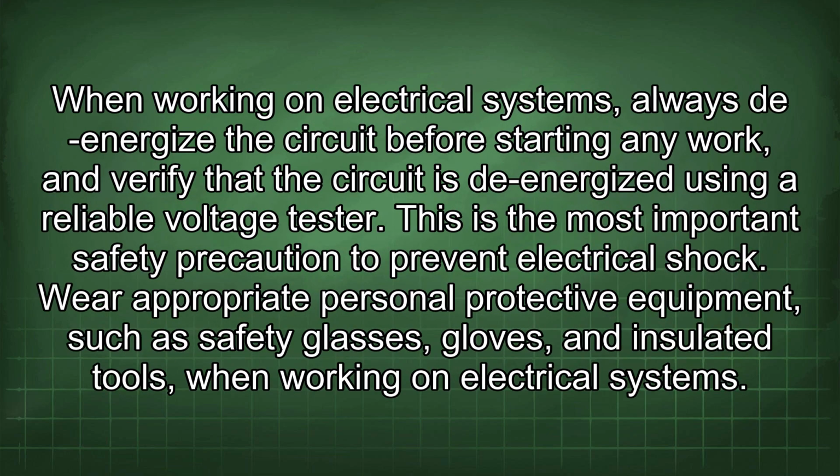When working on electrical systems, always de-energize the circuit before starting any work and verify that the circuit is de-energized using a reliable voltage tester. This is the most important safety precaution to prevent electrical shock.